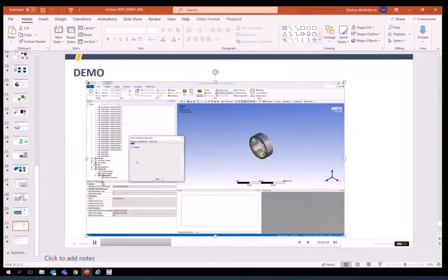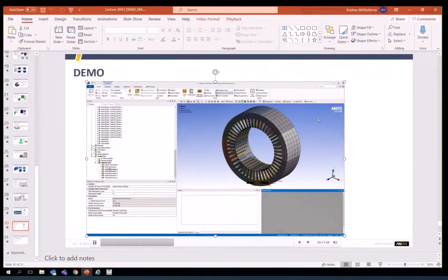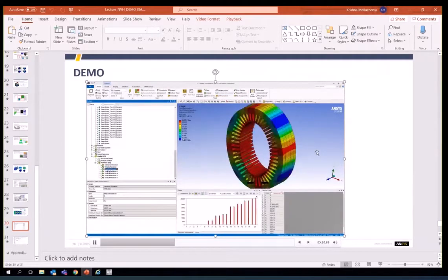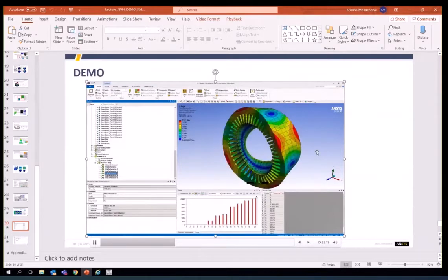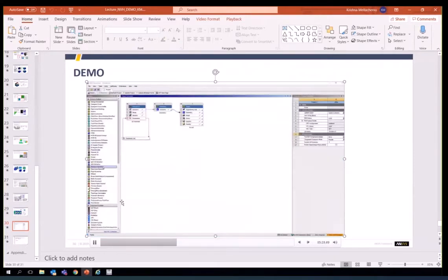And we can solve. So we are not defining any fixtures. It's going to mesh, and it's also going to solve for the modes at once when we solve it. You can see the first 6 modes are almost zeros. Basically, of course, it's not constrained, so it'll have some rigid body modes in the beginning. You can solve for some of the modes here or all of them if you want. So I'm just plotting the deformation for some of the modes here.